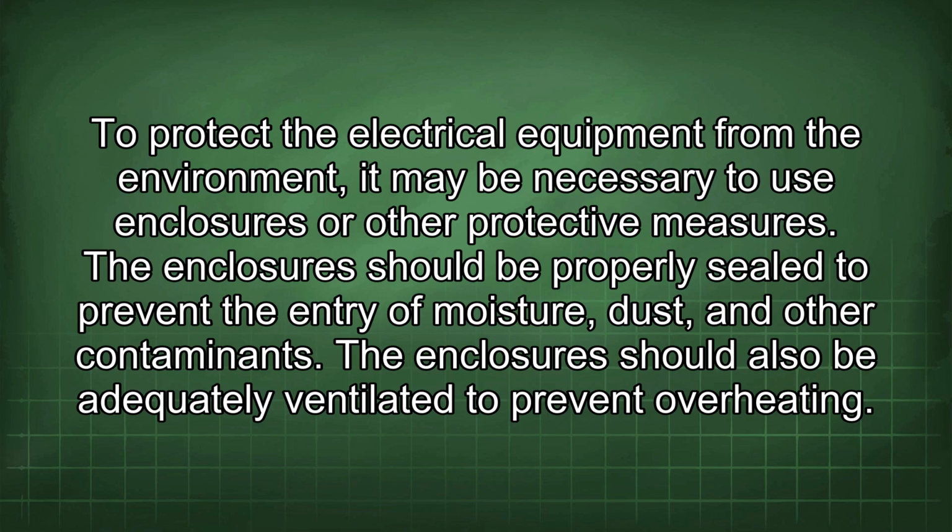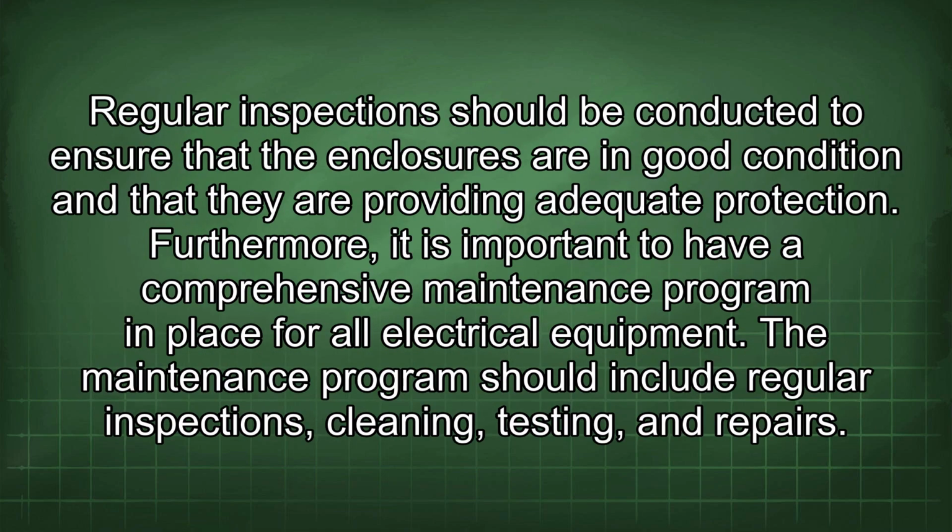The enclosure should be properly sealed to prevent the entry of moisture, dust, and other contaminants. The enclosures should also be adequately ventilated to prevent overheating. Regular inspections should be conducted to ensure that the enclosures are in good condition and that they are providing adequate protection. Furthermore, it is important to have a comprehensive maintenance program in place for all electrical equipment.